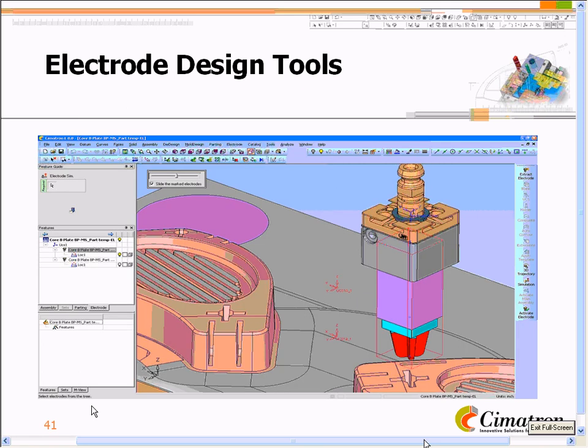Likewise, here's the bill of materials. With one click it says, show me all the components, show me how many, show me what they're made of. And there's a stock size function that will generate overall sizes for order, to make my slides and lifters and things like that, or cavity inserts.